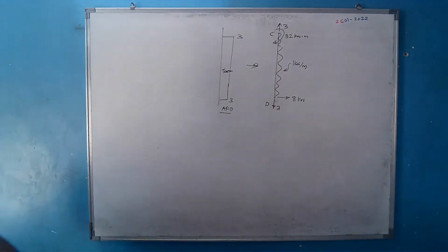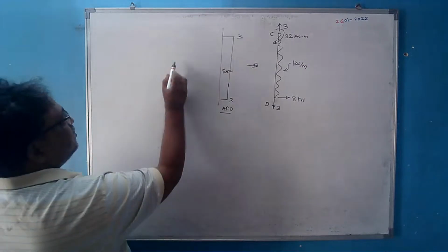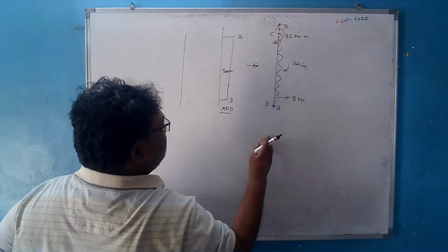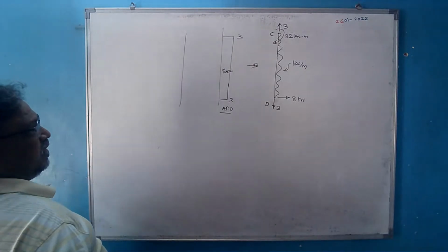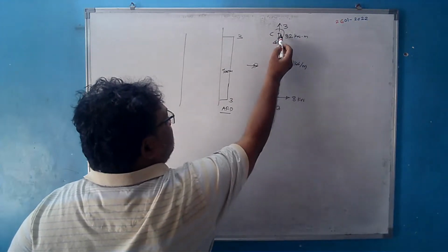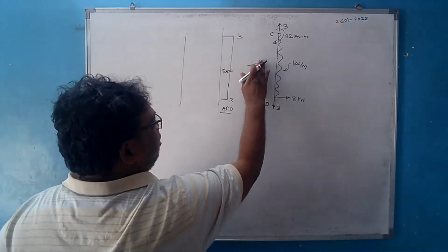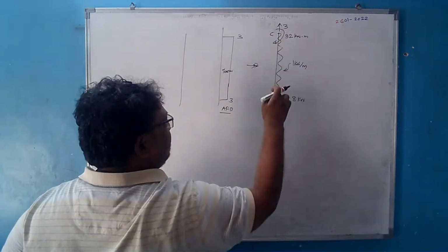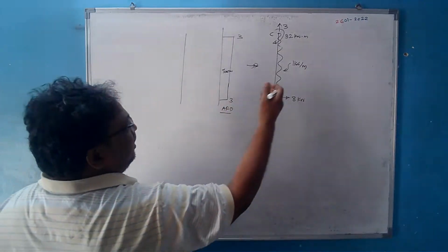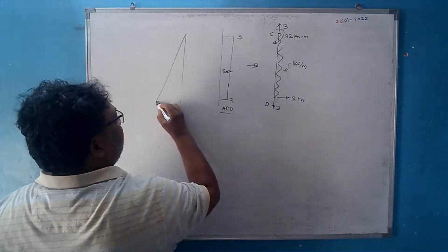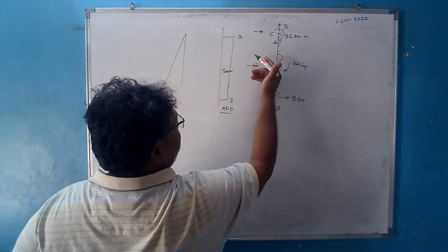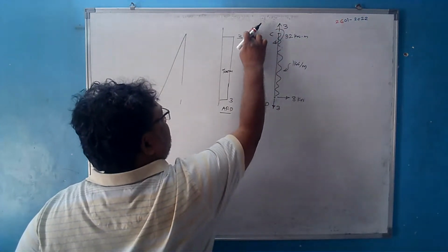What about the shear force diagram? See, from here, there is no force acting perpendicular to this member. A force which is perpendicular to the member contributes to the shear force diagram. There will not be any contribution of this couple in the shear force. The shear force will be here because of this UDL which is acting horizontally. From here to here there is a UDL and in between there is no other force acting. When the uniformly distributed load is acting, the shear force variation will be linear, and it is acting left, so it is negative. If there were something here, that would be positive, because this UDL will be negative. But there is no horizontal force acting here, so there is no positive shear force.